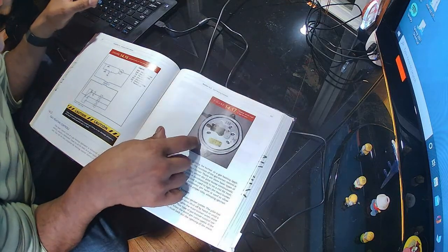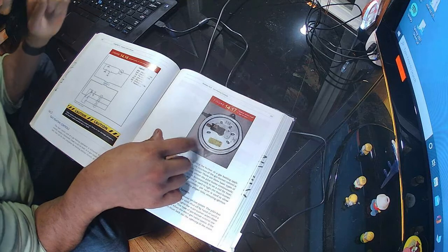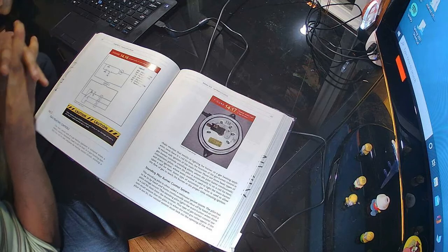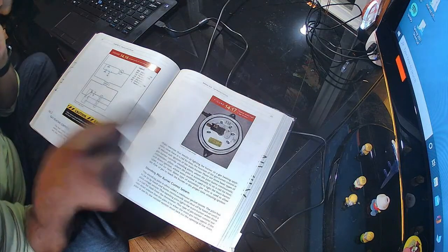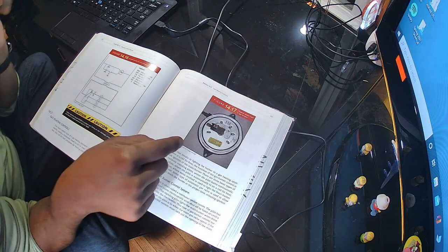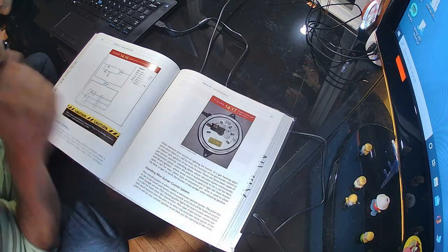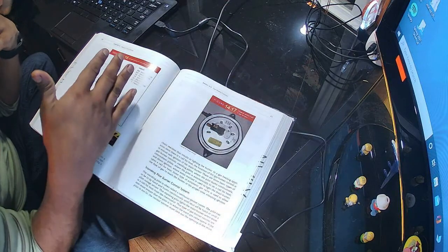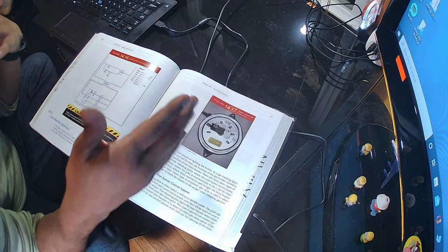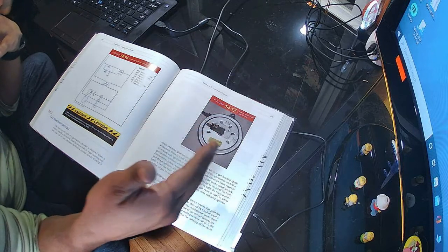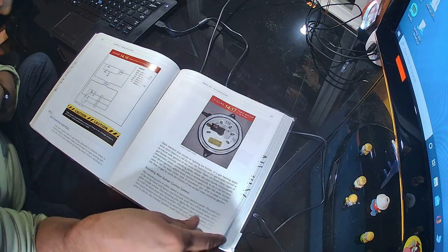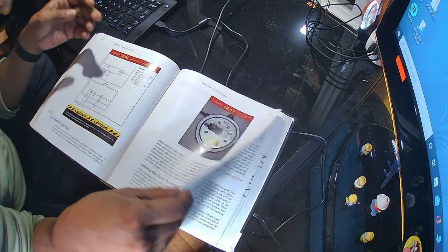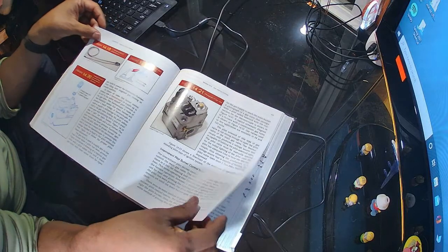This is really good. This is a pressure switch and it's used in gas furnaces. You'll see this a lot. Once you turn on your gas burner, this will indicate that there is flow in your pipe. So first you turn on the fan and you open the flue pipe. If there's the proper negative pressure, then the gas will turn on. So this is a very important switch to have. It's a diaphragm and it's on and off to indicate that there's a flow in the system.